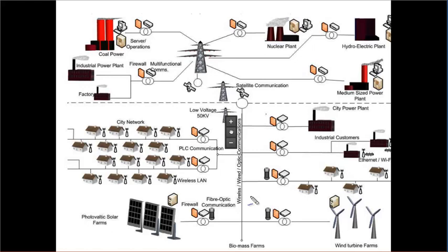And in our second lesson, we talked about telemetry, specifically what telemetry is, which is measuring all these pieces of information that we need to know and reporting them back to a central location. And so in telemetry we talked about the concept of data tags. So if I were to say I want to monitor the voltage on a transmission line, I would create a tag for that voltage, and that tag would have certain metadata associated with it, like a minimum and a maximum and engineering units and things like that.